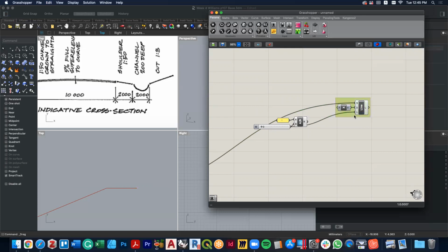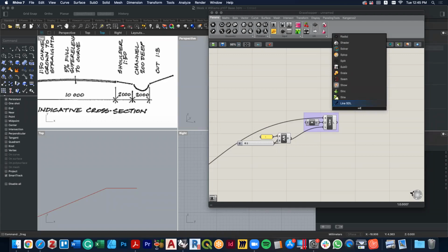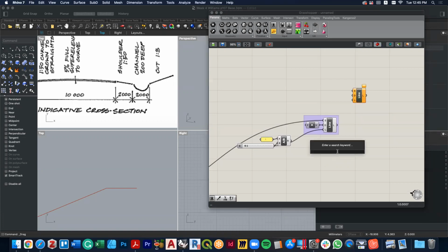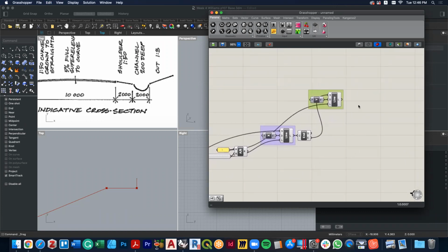And now I'm going to do the same process again. I'm going to do an SDL. Again, I could draw this totally differently to how I'm doing it, but I'm improvising it. At this point I want to get to the endpoints, same process. So, endpoints, we know that that's the end there. The direction this time is Y, unit Y. And now I'm going to move the 1. Sorry, wrong way around, I messed that up. That's actually the direction. The length is 1. And so now we have essentially another 2 lines, construction geometries, and I go to end again.